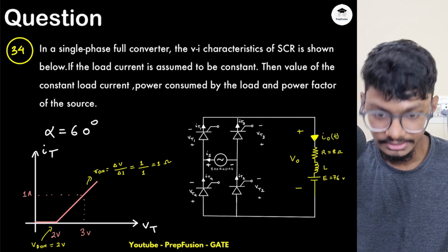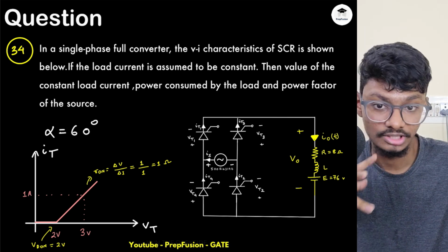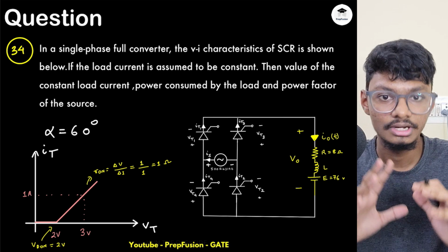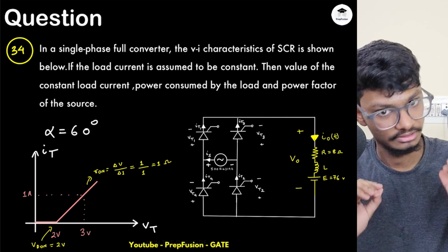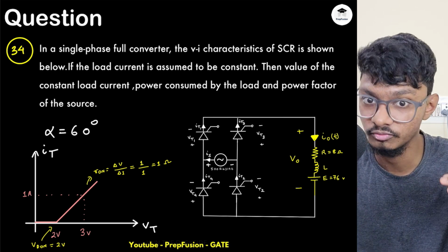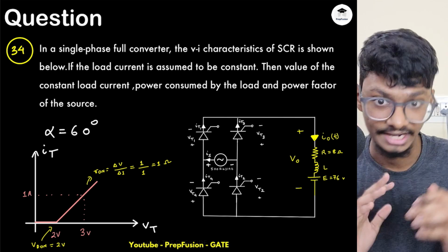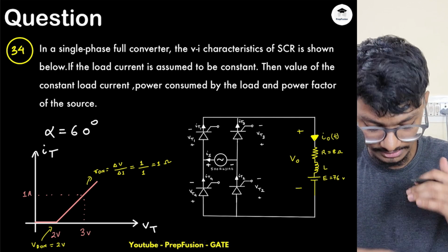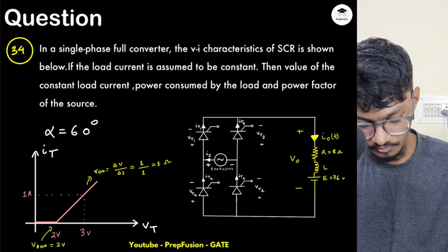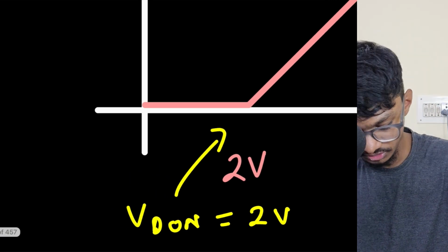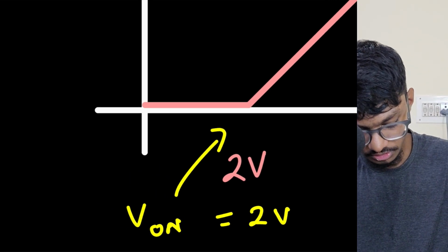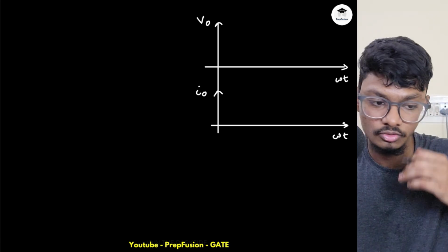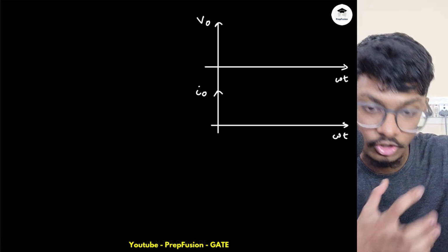Now what I can say is that I know the switch. Now let's for a second solve this if my SCRs were ideal. Because up until now, we have been solving for the cases where my SCR is ideal. We haven't thought about the switching losses, this R on and this V on. This should not be VD because this is not a diode, so this should be only V on. First, assume ideal switches, because once you assume ideal switches, then you incorporate the complexities.